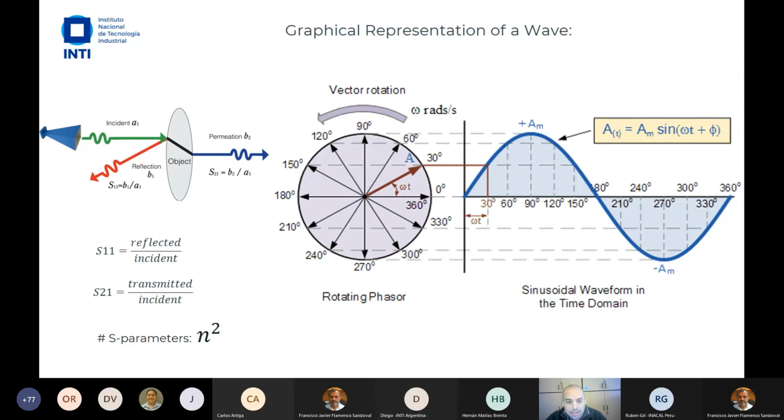Basically, an S parameter is what impedance is at low frequency. It gives you information about mismatches in a transmission medium. And mathematically, it's a ratio of two waves. Because a division of two complex numbers is another complex number, an S parameter is a complex number too. That means it's a two-dimensional quantity.